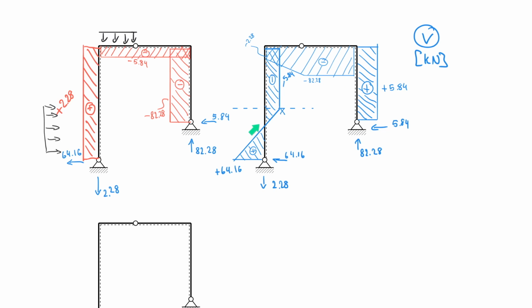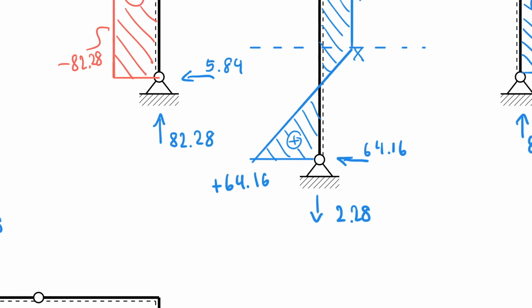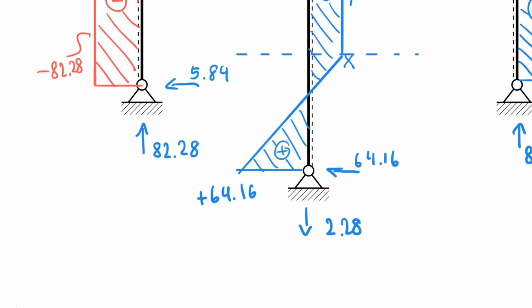Last thing for me to do is to calculate pretty much this distance here, because remember that where the shear force goes through 0, my moment is maximum, and of course I want to calculate that. So I want to really understand this distance here. So let me zoom in there. And I have these distances. And you can find that in many ways, similar triangle or something like that. So x actually happens to be 3.208 meters.